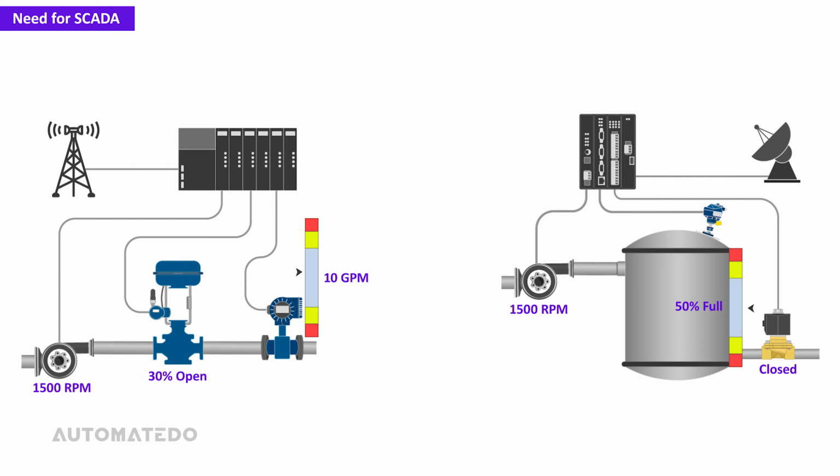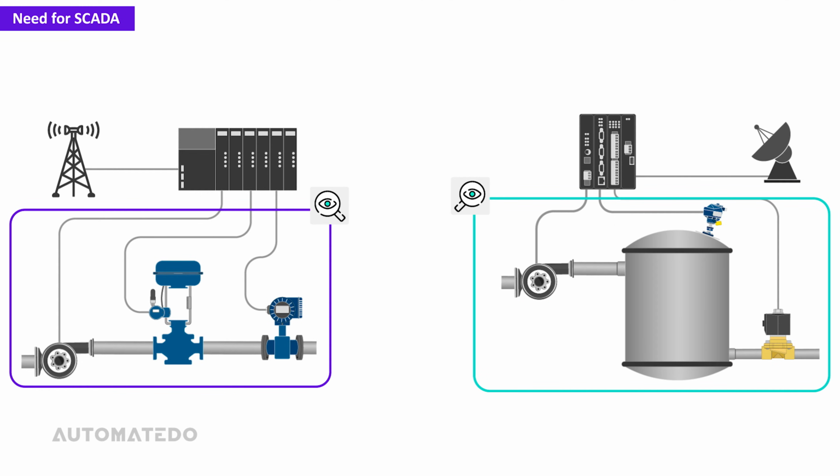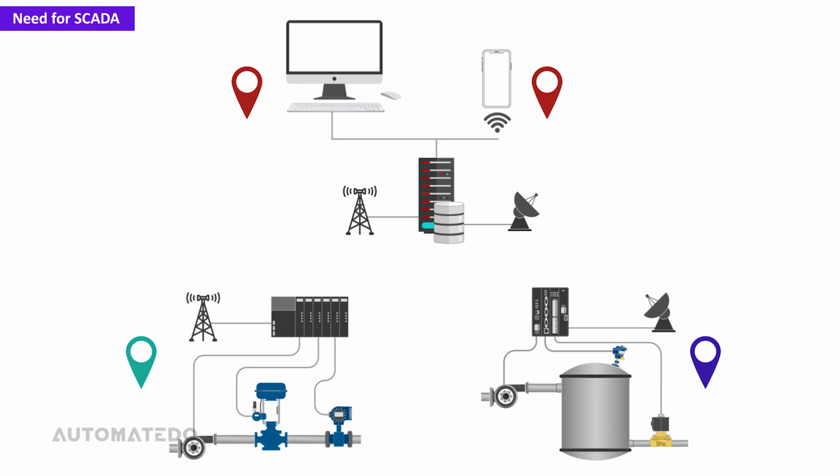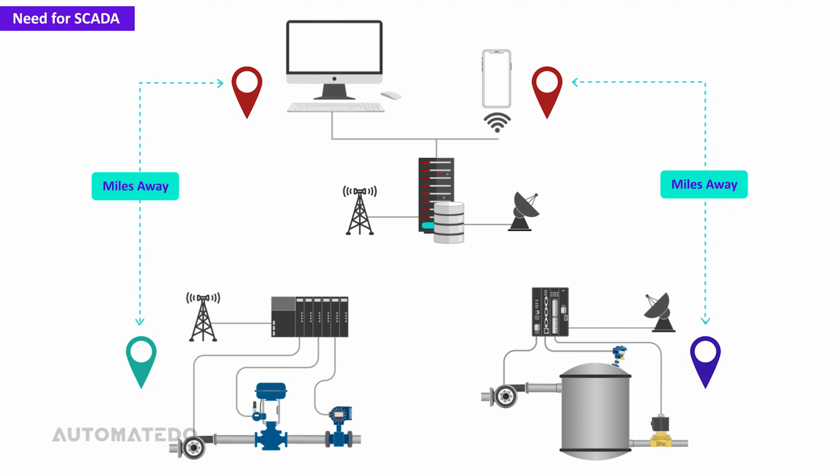First, where you need to visualize real-time data on connected equipment located across a plant. For example, a flow rate of a pipeline, or how much a control valve is open. Secondly, SCADA is required where you need a safe environment and want the measurement parameters to be within specific ranges to avoid harmful circumstances. Thirdly, where you want to supervise and control numerous industrial sites while you don't have sufficient personnel to cover them, SCADA is needed. And fourthly, SCADA is a suitable solution for remote operating capability, meaning if industrial sites are miles away from your control center, you can still have visibility and control over your processes.